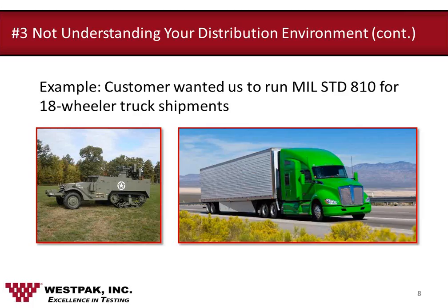If that were the case, then we could ask them about what vibration profile they would want to use out of MIL-STD-810. And they said, no, we're going to be selling this just out on the road in America, so it's going to be transported via truck across the country. Talking to them further, we discussed different vibration profiles, and they decided, with our recommendation, to use ISTA 3A over the road and pick up delivery profiles per the ISTA 3A test standard.